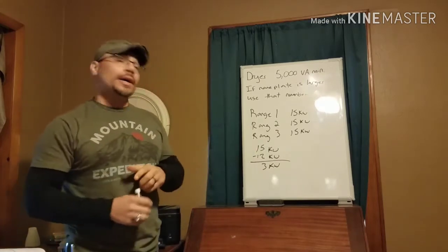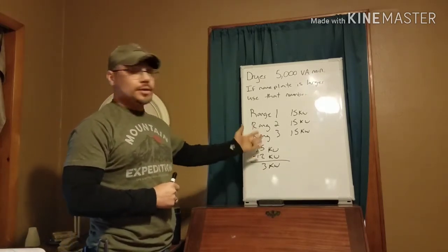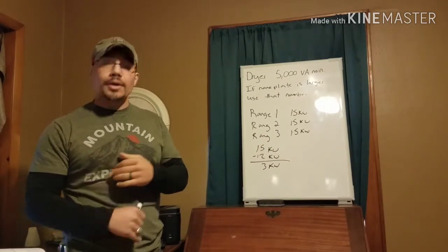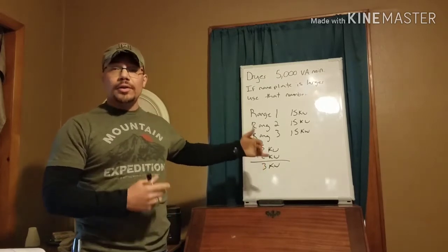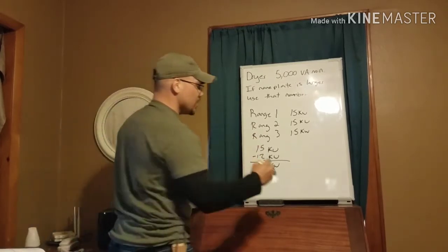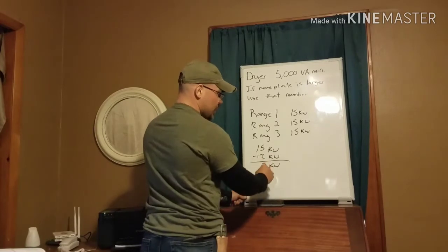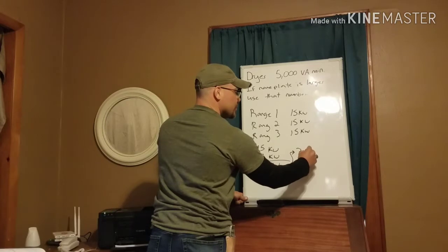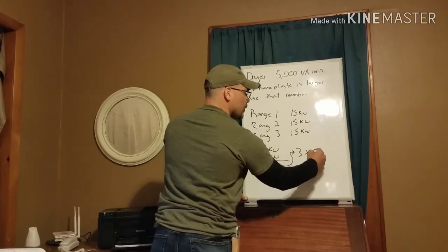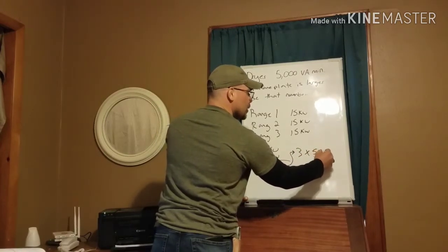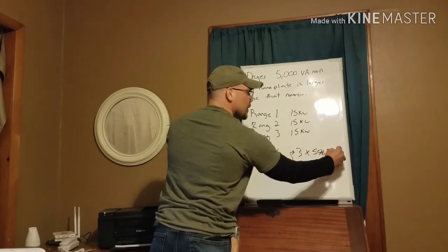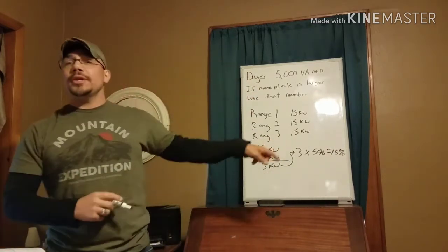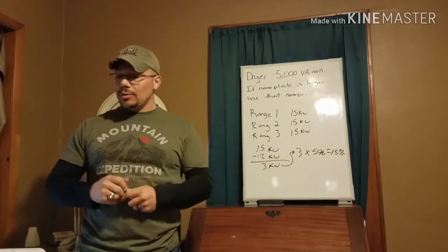Okay, so 15 kilowatt minus 12 kilowatt equals 3 kilowatt. It says on note 1, for every 1,000 over the 12 kilowatts, there is going to be an extra 5%. So we take our 3 times 5% equals 15%. That 15% then needs to be added to our demand factor in column C.